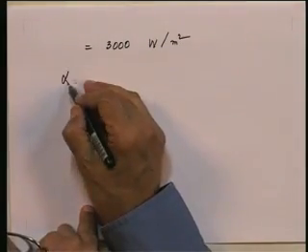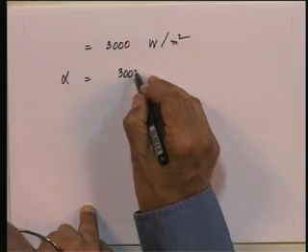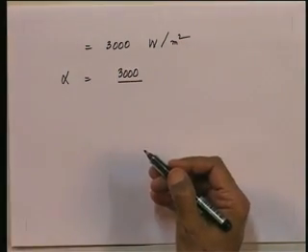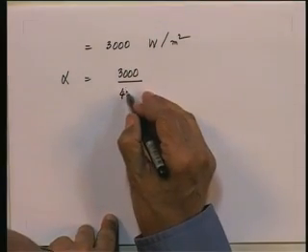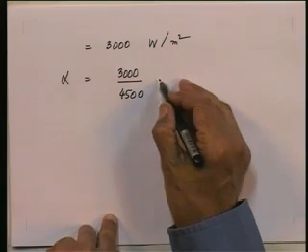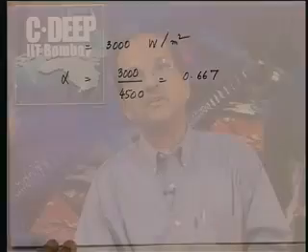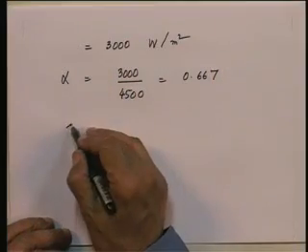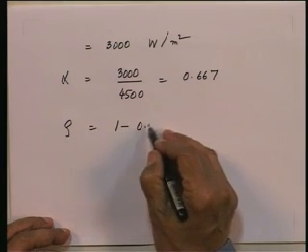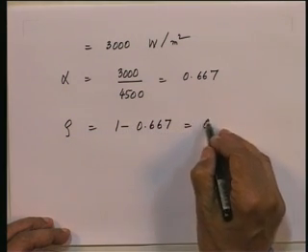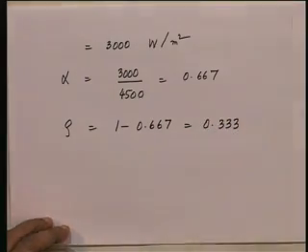So, therefore, what is alpha? Alpha is nothing but 3000 divided by the incident radiation. The incident radiation you know is nothing but 4500, 750 into 6, and therefore, alpha is 0.667, and because the surface is opaque, it follows that rho must be equal to 1 minus 0.667, that is 0.333. So, you see here is a very simple problem in which we have illustrated the ideas of all these quantities which we have defined today, namely the absorptivity and the reflectivity of a surface.